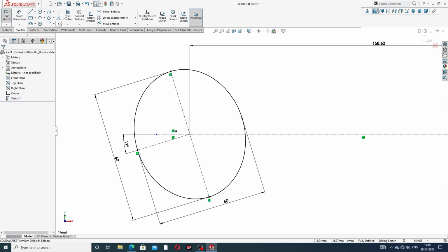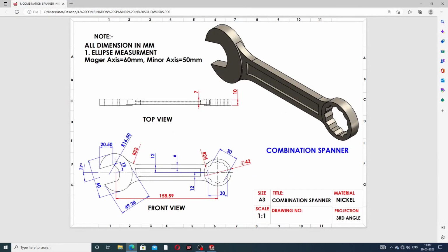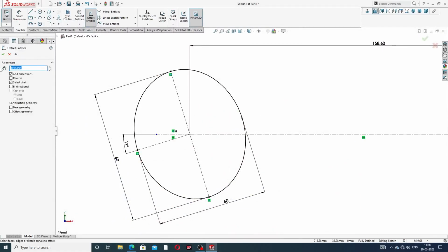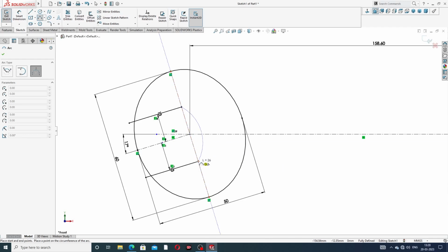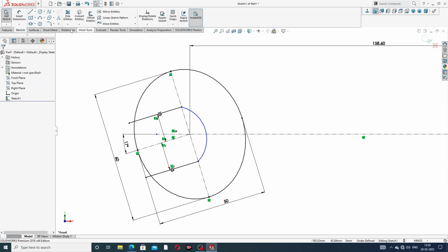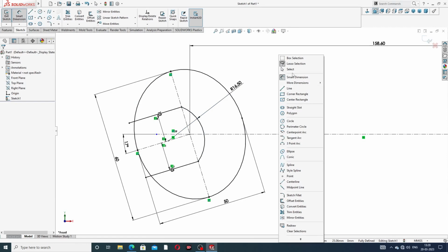And then use the offset command. This distance is this, and the offset is 13 millimeter. This curve is drawn here, and this curve is 16.5 millimeter, and this is 13. This direction is 13 millimeter. Select bidirectional and select chain. Click OK. This is perfect. And use this 3-point arc, connecting this point to this. This creates a curve, and the align dimension is 16.5 millimeter, perfect.